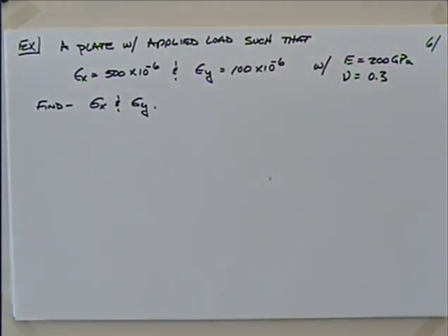Okay, so this is a problem that comes up a lot. We take something with a load on it, maybe a piece of machinery or something, we're doing some preliminary design on, some testing on, and we measure the strains. We're not particularly interested in the strains, we'd like the stresses. Stresses are usually fairly hard to measure, strains are usually pretty easy to measure.